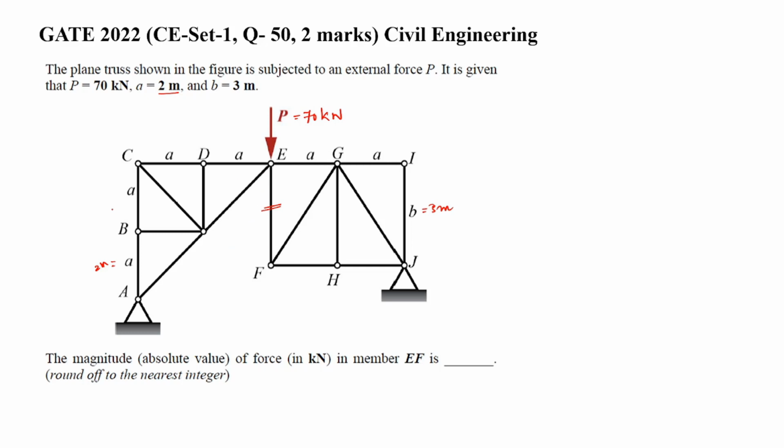See, a joint means at every joint we can find out the forces in the members which are joining at the point. Method of sections means we can cut the total truss into two parts, then we can deal with that. Before doing anything, we have to find out the reactions first of all. So let me first draw this figure as it is, or else I can draw here itself.